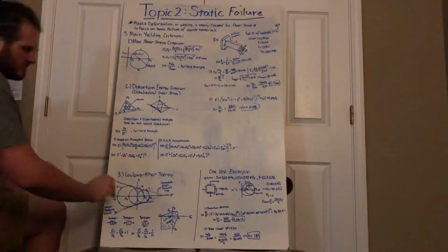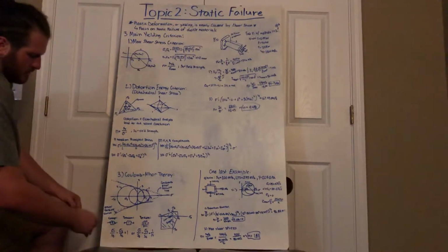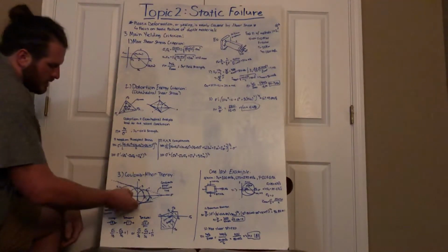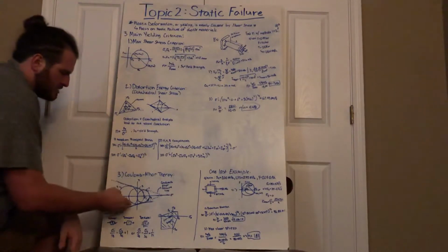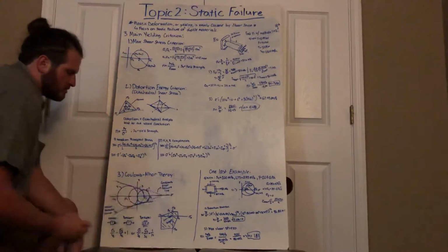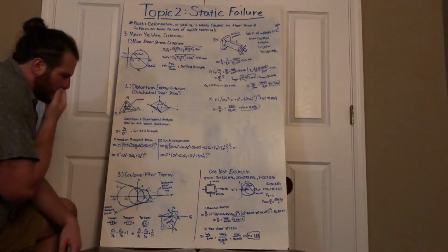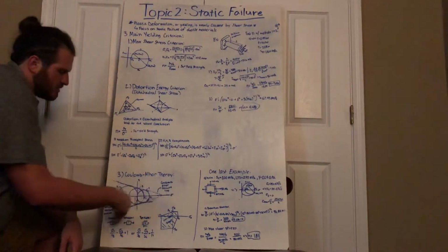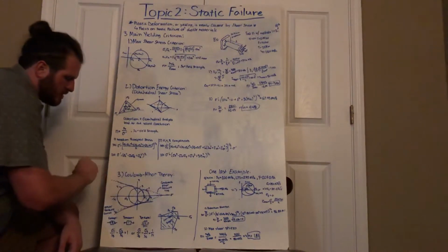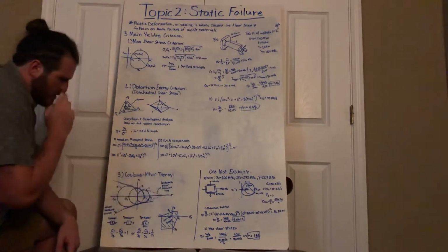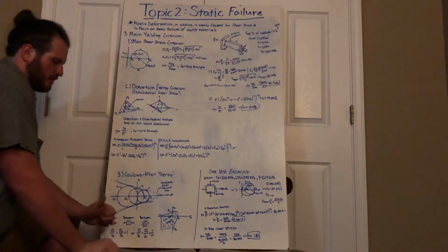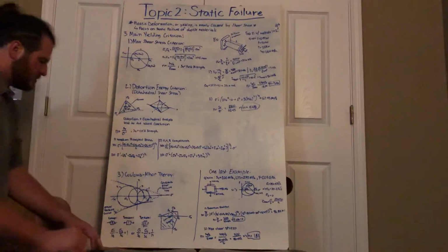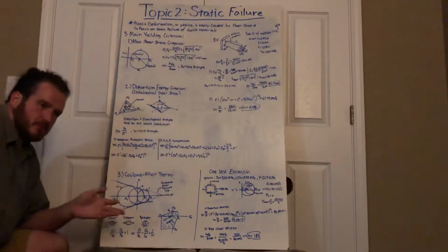So, superimposing them into each other, we can apply a Mohr failure curve to them. So basically, as it comes through here and touches each of these circles and goes through. Now, as we're applying that, we can approximate those curved lines to the Coulomb-Mohr failure lines, which are these straight dotted lines here. And those are going to help us to find our principal stresses that we would need to, say, find a factor of safety later on, or find the other principal stresses.